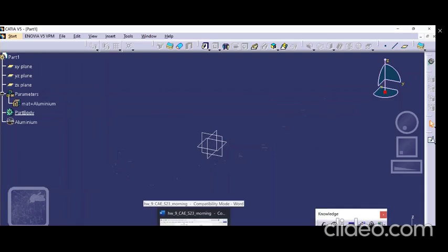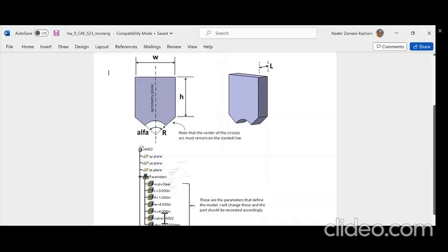All right, so let's go ahead and create our parameters. I'm going to use this order, in that order, and a bunch of numbers which are listed here. If I want to maintain that order, I better write these things down. L is 3, R is 1, W is 4, H is 4, and the name is whatever, that dummy name, 002, and alpha is 100 degrees. Okay, good. So I go to CATIA.